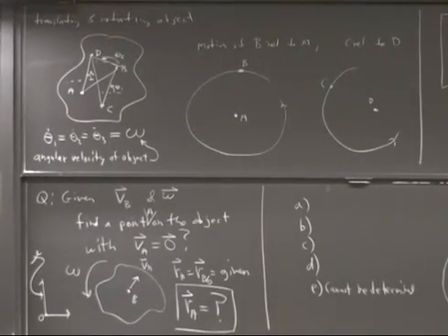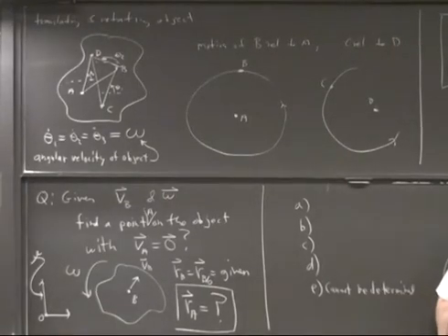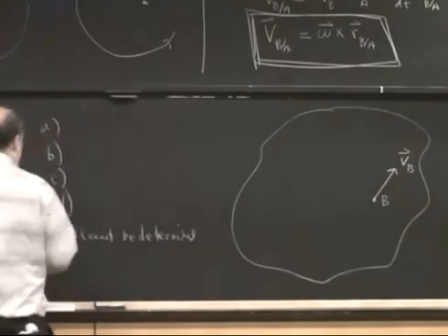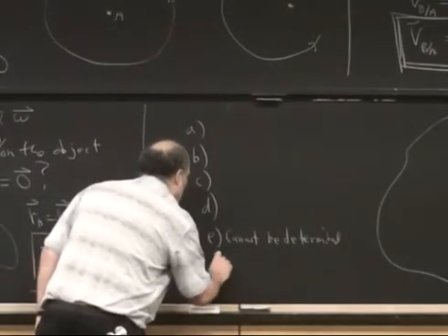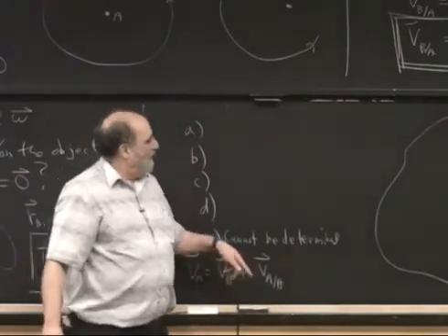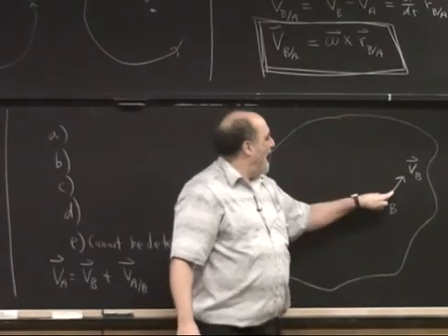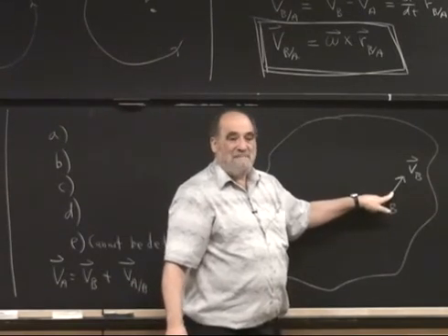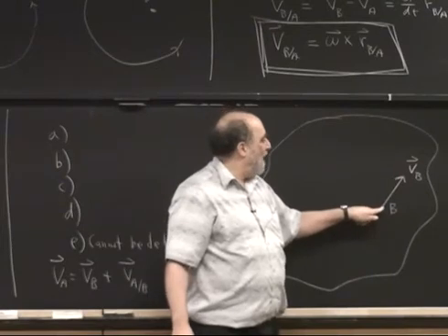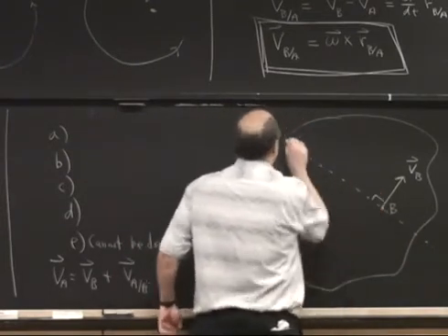Okay. So what we know is that the velocity of B is given to be this thing. And we know that all the points here are going in circles around B. So we're trying to find the velocity of A, which is equal to the velocity of B plus the velocity of A with respect to B. I've done it backwards here. And the velocity of A with respect to B for any candidate points here is tangent to a circle. And we want to add that to this and get 0. So it has to be that the tangent to the circle is anti-parallel or parallel to this line. And the points that have velocity relative to B which are parallel to this line are the ones that are on the perpendicular line. So this point A, if it's going to be somewhere, has to be on this line.